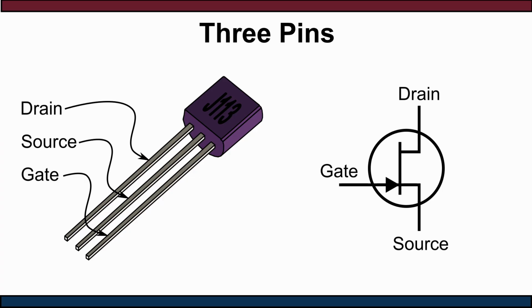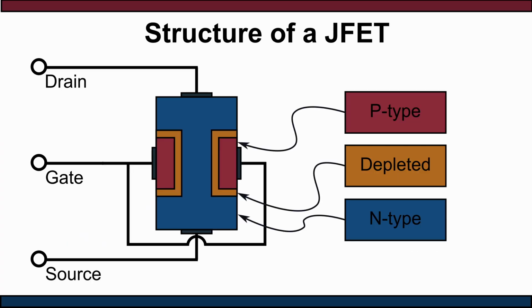To understand what's going on, I want to start the explanation from the physical processes in the JFET transistor. In the illustration we see a box with 3 terminals. The first terminal is connected to p-type semiconductor, the other 2 to n-type semiconductor. If you don't know what p-type and n-type silicon are, you can think about p-type as a material with free charge particles, but opposite to electrons, positively charged. N-type silicon has free electrons with negative charge.